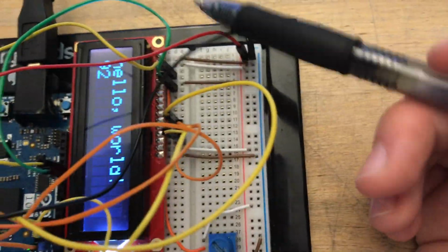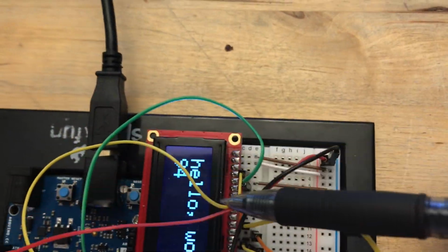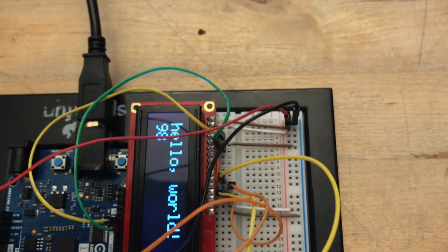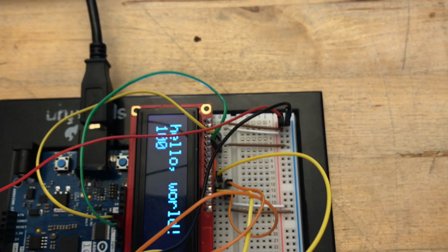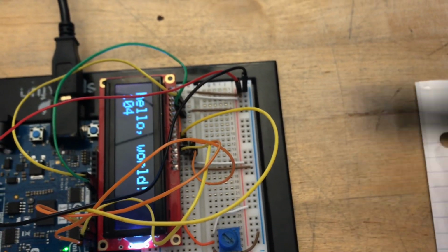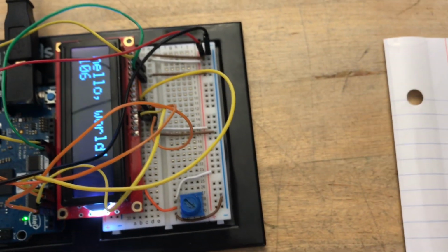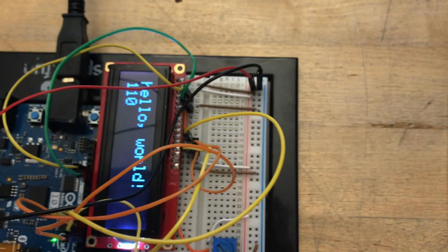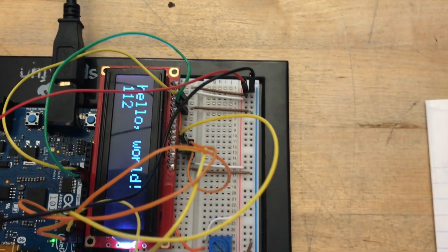The next thing is this yellow wire here, which connects the fourth pin on the board to the data and control register select pin. H is for D0 to D7 core display data, and L is for D0 to D7 control data. So that's what the yellow wire connects it to.